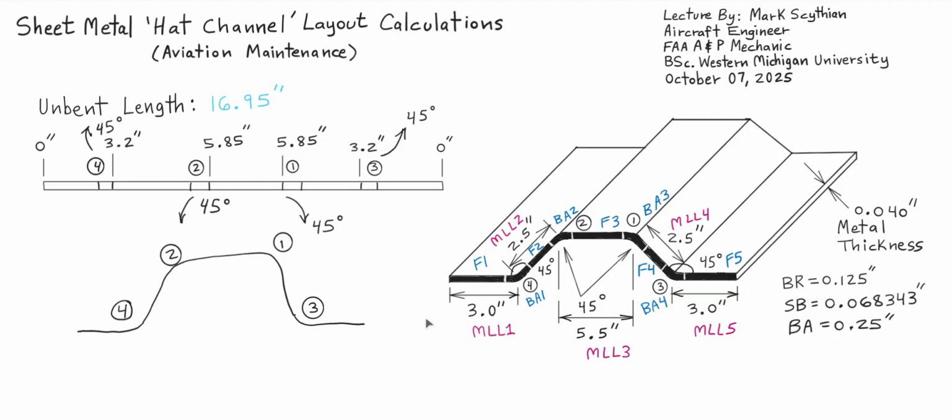So if you're a little bit over or a little bit under, as long as you're within 1/32 of an inch plus or minus on both sides, so it's a double of 1/32 inches plus or minus times 2 on both sides. You could actually be as much as a 16th off, but only on one side at a time, 1/32 inch. So if you're slightly over or under, that's fine.